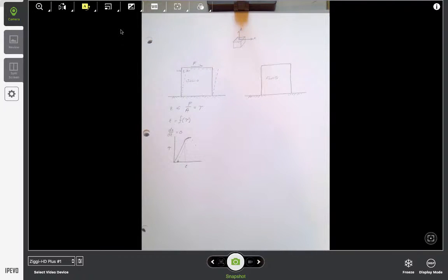So to summarize that, we have the properties that the solid will deform, but not continuously. When we apply stress, the deformation is proportional to that stress, and that's called the strain. The strain is some function of stress, and assuming the solid does not fail, then that deformation is largely time invariant, and assuming we don't go beyond the elastic capacity of the solid, the process is reversible. When we remove the shear stress, the material returns to its original position.